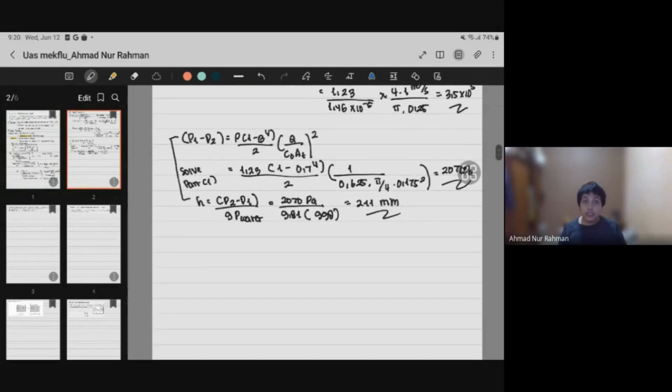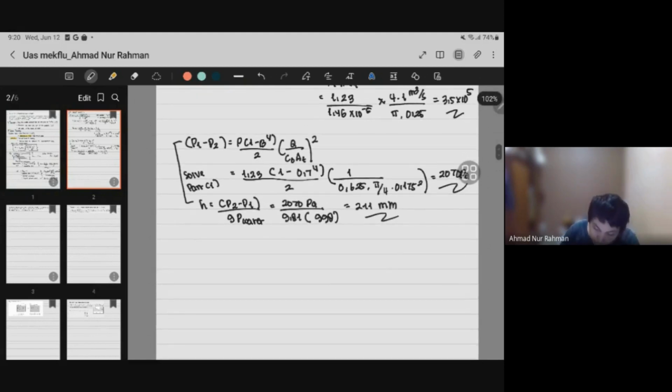This is lower than the maximum pressure difference, so the second guess will be made using a smaller orifice diameter, which corresponds to a beta of 0.6. The orifice coefficient at this diameter ratio is 0.615. The same calculation as above is carried out, and the resulting pressure difference and manometer height are found. Because we make the diameter smaller, the pressure gap is increased and the height is increased too.